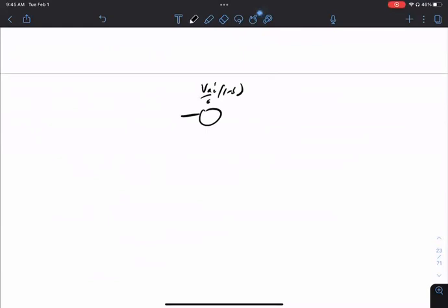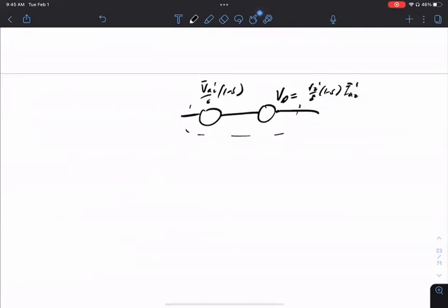So this is one part of the developed power. This is coming from VA2 prime. And another part of developed power comes from VD. This is R2 prime times (1 minus S)/S times IA2 squared. Right? So developed power is how much power gets developed in these two things together. Okay?